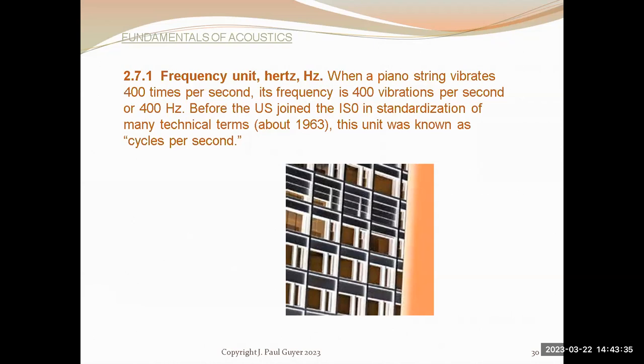The beam fails. So you want to stay away from that natural frequency. It's extremely difficult to calculate the natural frequency of any mechanical or structural system; it's largely determined or estimated by laboratory and field tests.